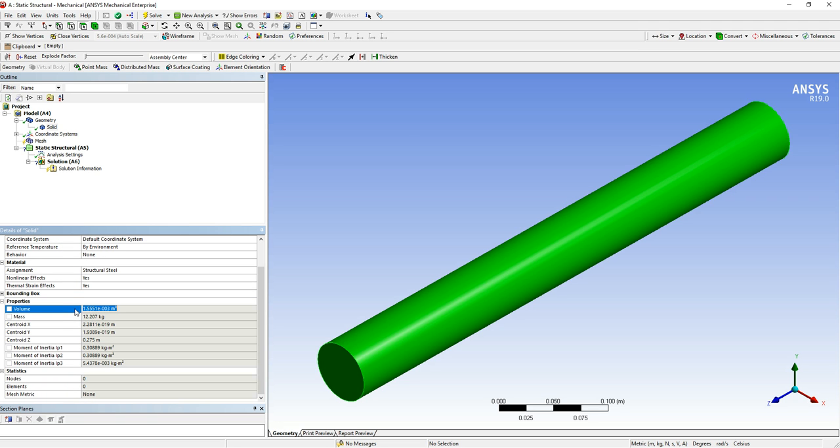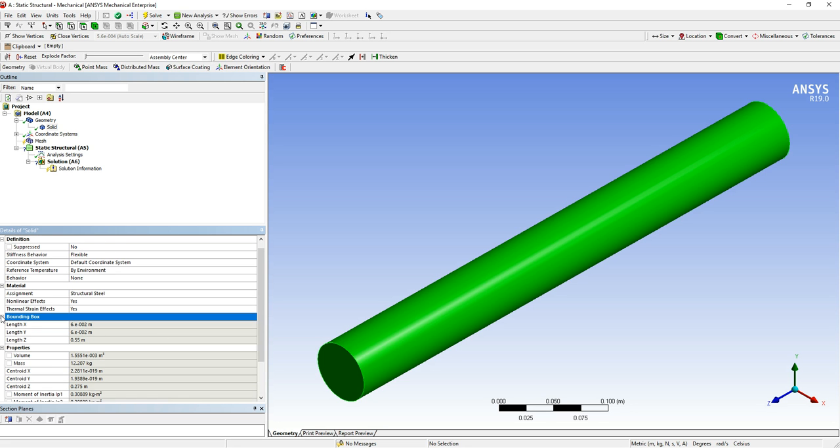Let me just bring that back. We have the bounding box. Within the bounding box, imagine that there is a box around it. The box around it is measured at this area, so this would be the pocket in which the component sits. Thermal strain effects, we've got that turned on. Non-linear effects, we've got that turned on. The type of assessment, going the type of material, sorry,